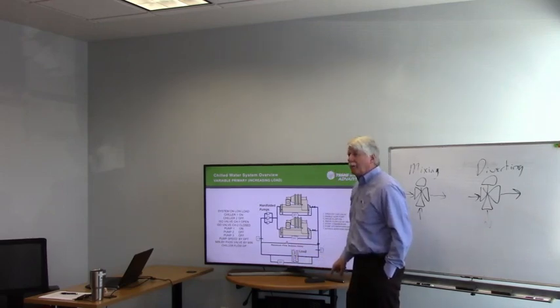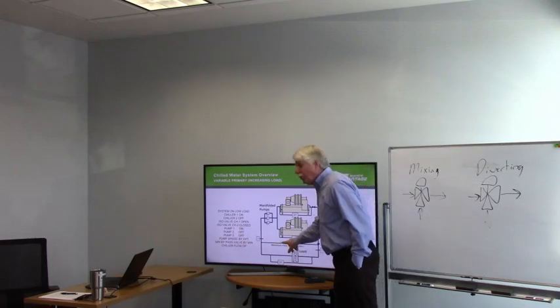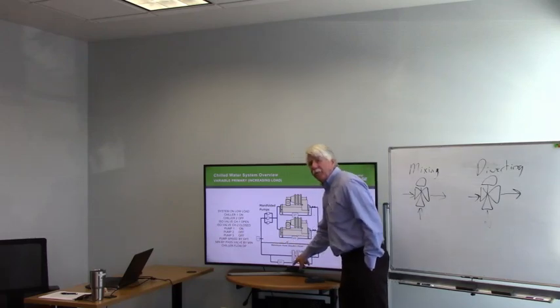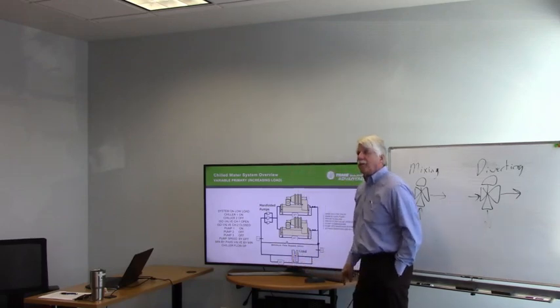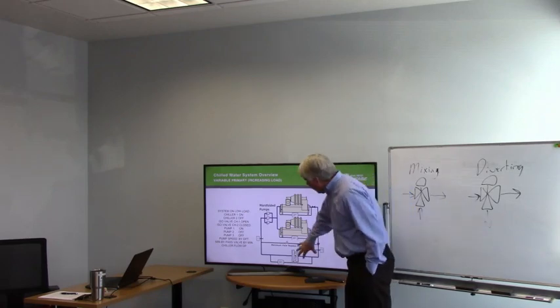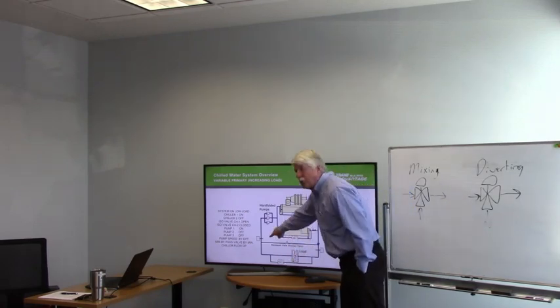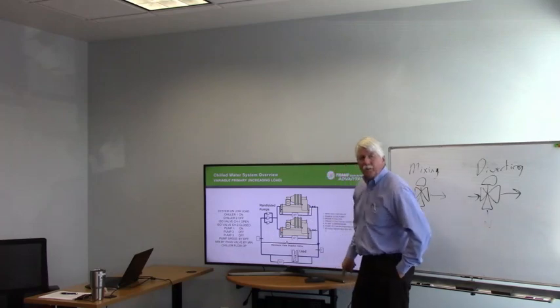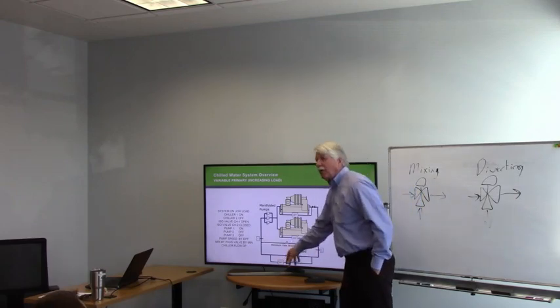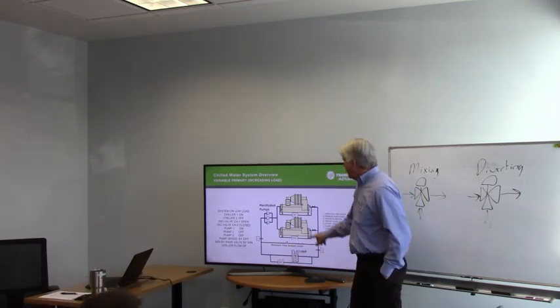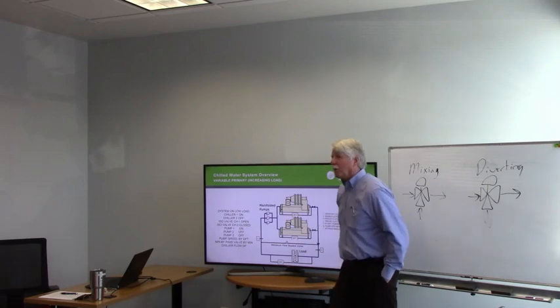Okay? Now, what happens when you open this valve out here? What happens to this DP? It's gonna drop. Does everybody see that? It's going to drop. Because suddenly water that was available out here is now short-circuiting back to the return. And you really don't care what's out in the load, because you gotta protect that machine. But it is really important that this thing work.